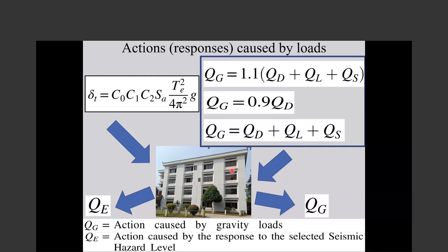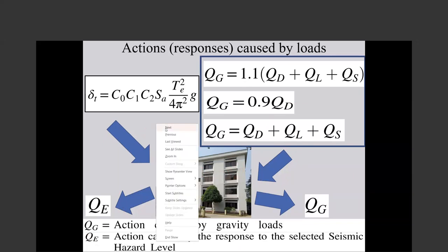If none of them pass the yield, the system is elastic. If some of them pass the yield, then we look at how much damage. And then we know we need the strengths, the capacities. But now is the demand. The demand is done. Now we have the effect of the earthquake on this.